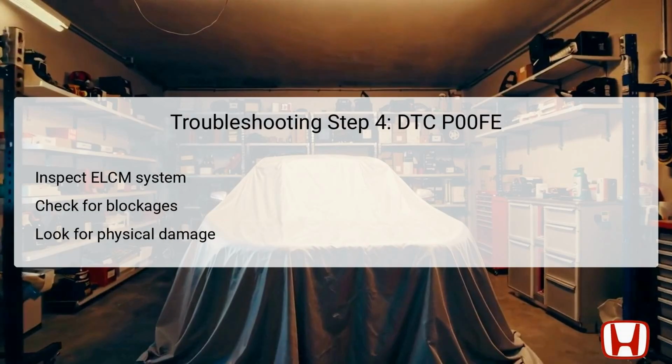The fourth troubleshooting step for addressing DTC P00FE entails inspecting the ELCM system, critical to the functionality of the EVAP system. This inspection requires examining the ELCM components for blockages, restrictions, or any signs of physical damage. Given the importance of the ELCM in maintaining proper venting of fuel vapors, any disruption in its operation could lead to abnormal readings that trigger the DTC.